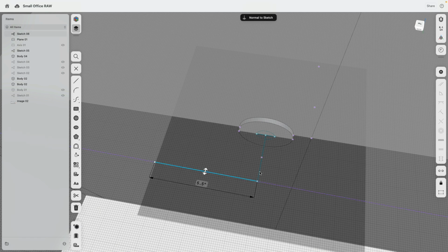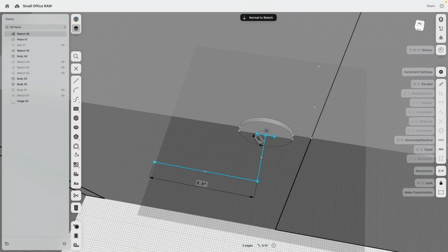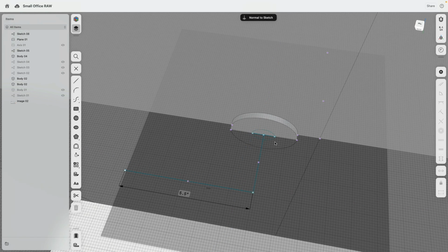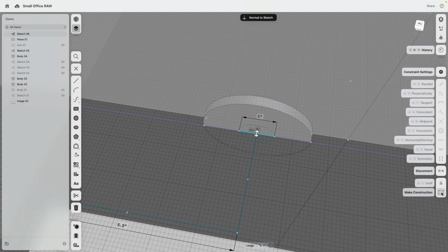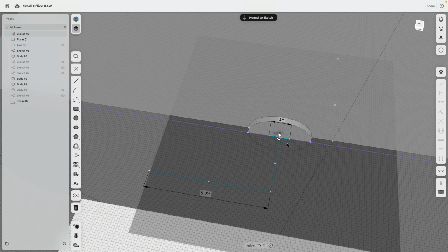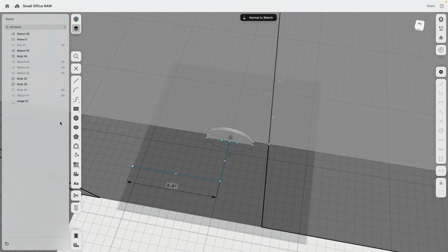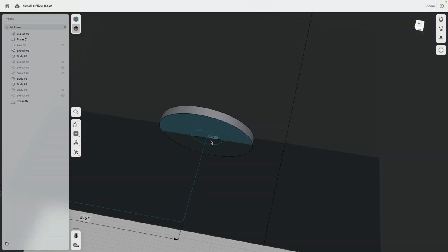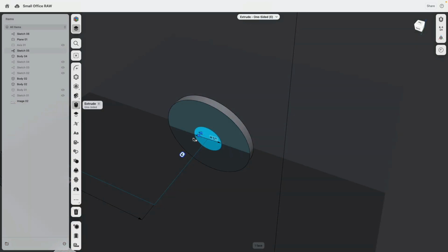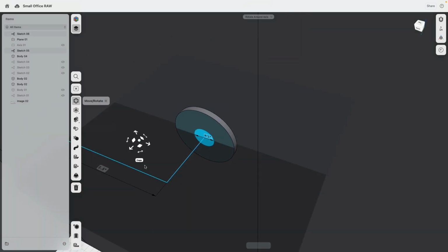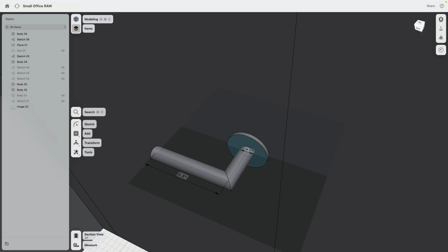Click and escape and escape. These all should be horizontal vertical, so they're 90 degrees. This is only a helper, so a construction line, because this goes left to right. I find the midpoint for this line to connect on. So now I can exit the sketch and simply say, so that profile along this line and that line, sweep.